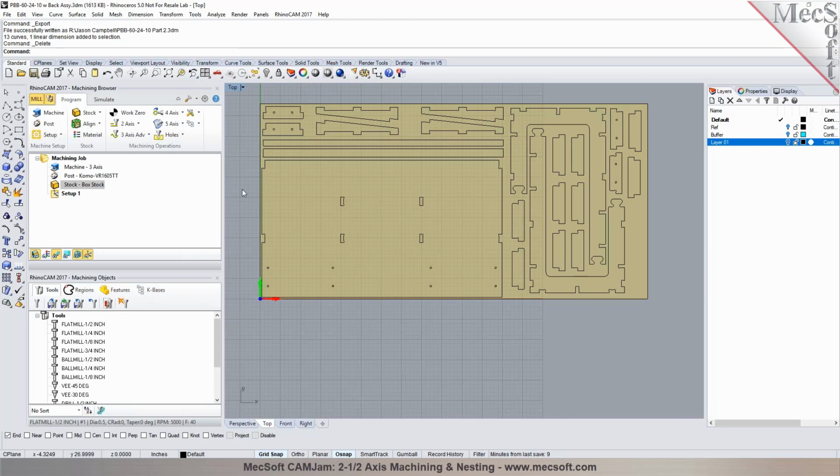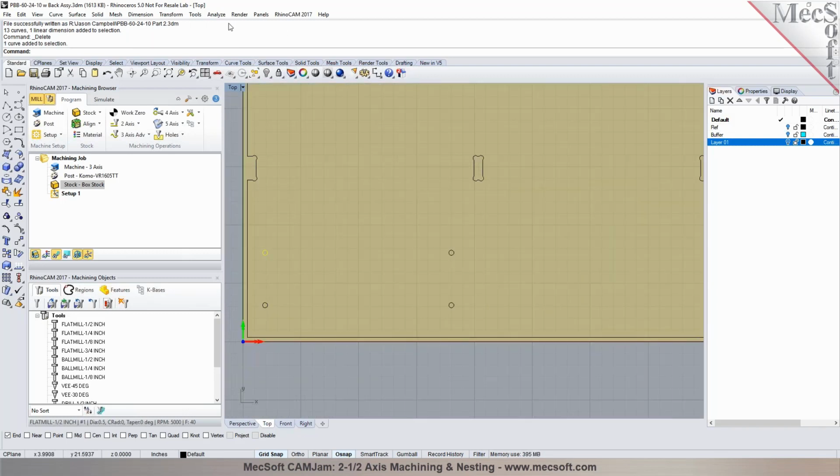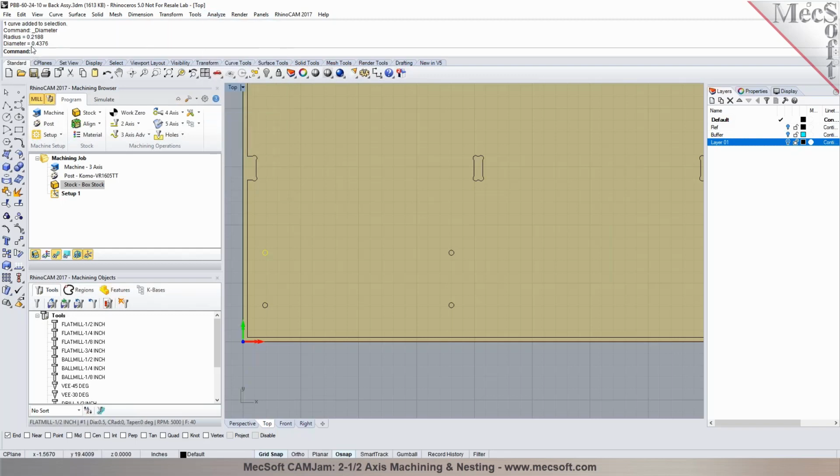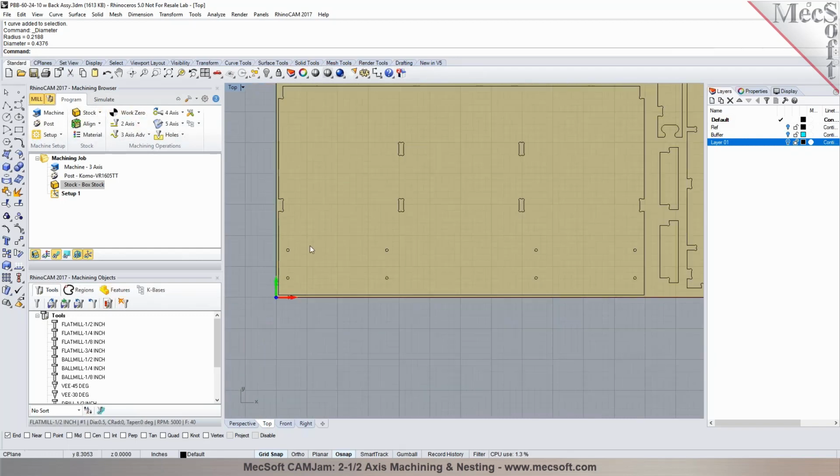Okay, all right. So we could do the same thing in here. So the next step I'm going to do is program the toolpaths in here. So since you already have these features in here, I'm going to go ahead and quickly check the diameter in here. So this one is 0.4376. So do you have a drill bit that matches the size of the holes, or do you want to use a standard size drill bit for it? We match the drill bits to the boring size.